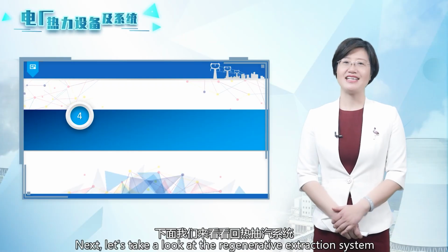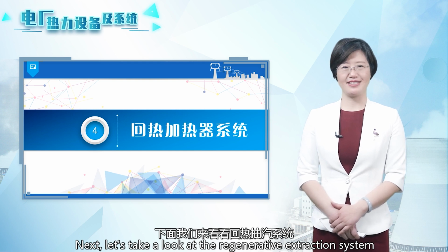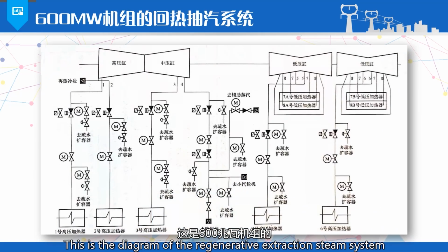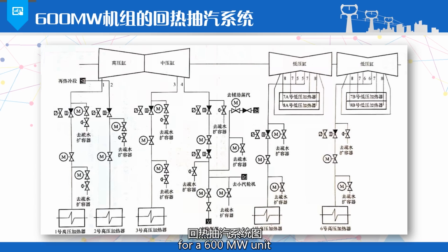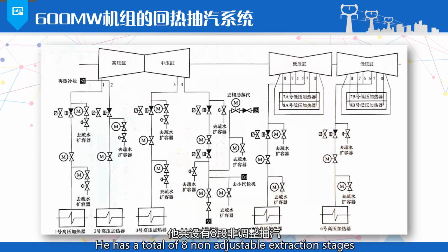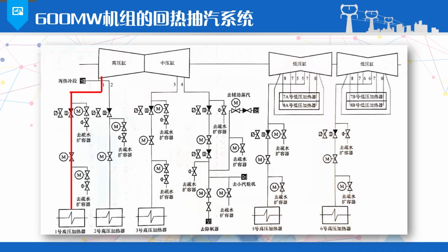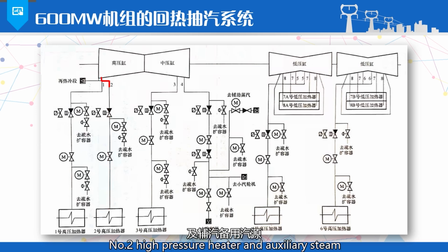Next, let's take a look at the regenerative extraction system. This is a diagram of the regenerative extraction steam system. For a 600 megawatt unit, it has a total of 8 non-adjustable extraction stages. The first extraction steam is led from the high-pressure cylinder to the number 1 high-pressure heater. The second stage of steam extraction is led from the high-pressure cylinder exhaust, supplying number 2 high-pressure heater and a backup steam source for auxiliary steam.